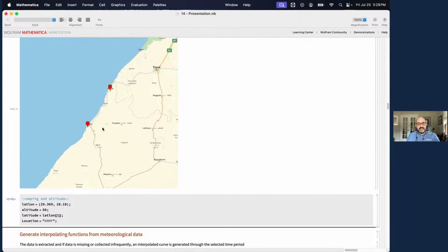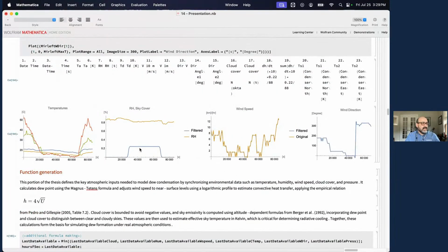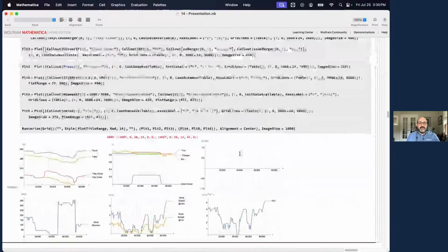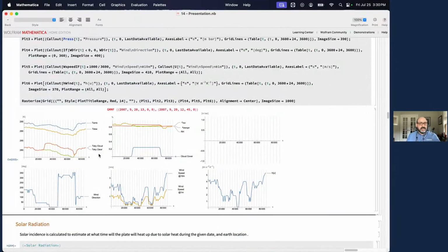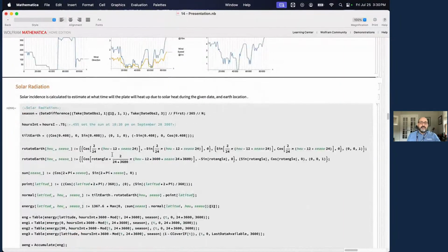So the data is injected directly from Excel to Mathematica, but Excel is discrete data. So now you want to convert that into an interpolated function, and each one of these curves is interpolated. The next step is to take your data and make it into a nice function. Now, if you want this data to be injected into the heat equation, it better have no steps, right? It has to be smooth transitions, right? That's something that you've got to think about. When you inject real data, it has to be smooth transitions. Otherwise, you're going to have trouble solving it in Mathematica.